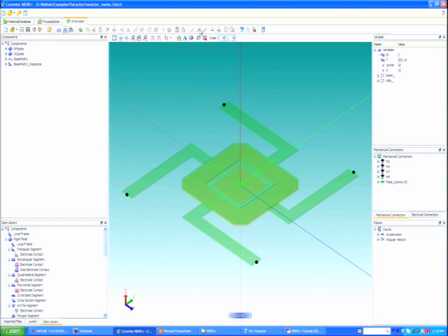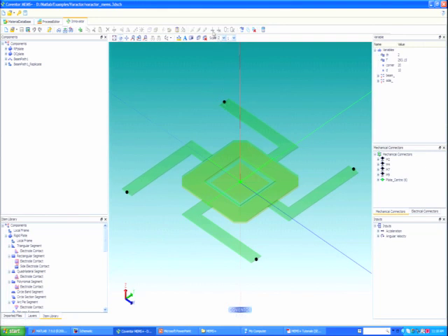That's the last bit you have to do, is define which connection points exist, and the black connection points are mechanical anchors. These are fixed to ground. So I can pick that point and I can say ground. It's been grounded already, that's why it's grayed out. So when I hit the ground symbol, you are mechanically and electrically ground. Well, this is a mechanical ground. It holds that in place. So that is now your anchor. Okay. So mechanically, I'm set. This is all I need to make my device.